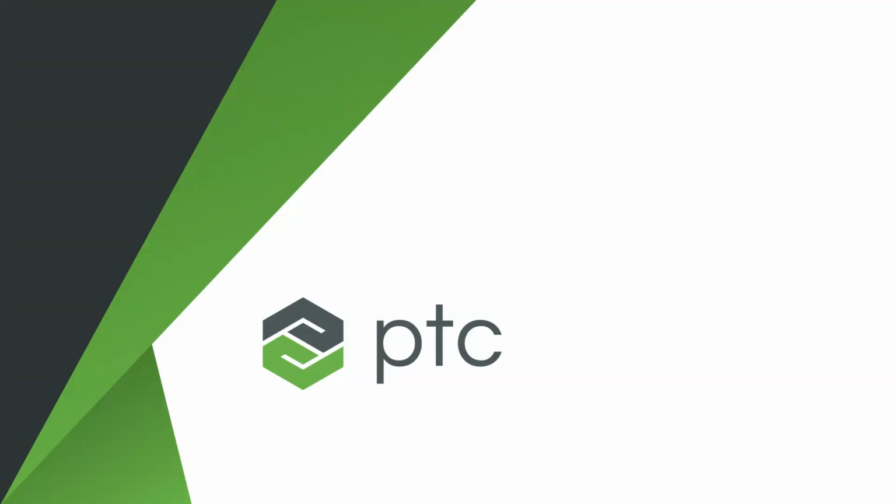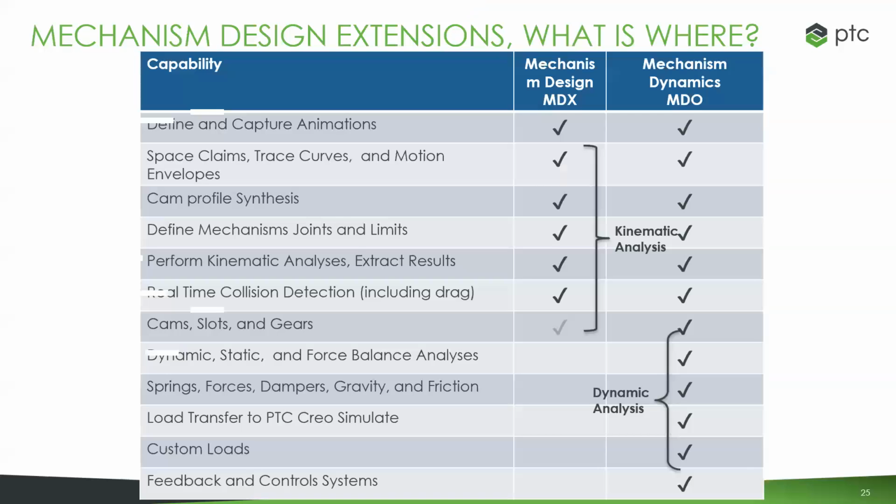Cool. And we got a request for the last slide with the different capabilities. Here we go. This is just laying out some of the different options that you have between your standard mechanism design capabilities in Creo. It's part of your tier 1 license of Creo versus what you're doing from a mechanism dynamics option. Really, the main difference is whenever you start to take into account your forces. That's the switch over from your standard mechanism capabilities, looking more at the motion, versus now taking into account the different forces as part of that motion.